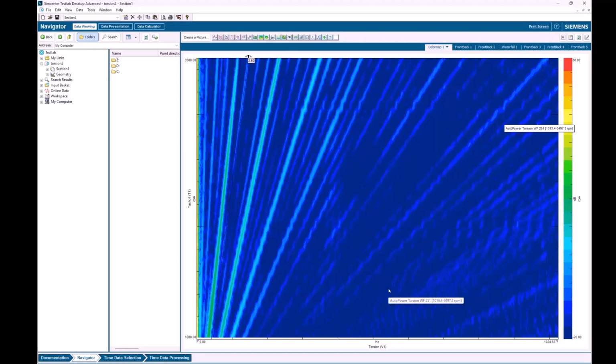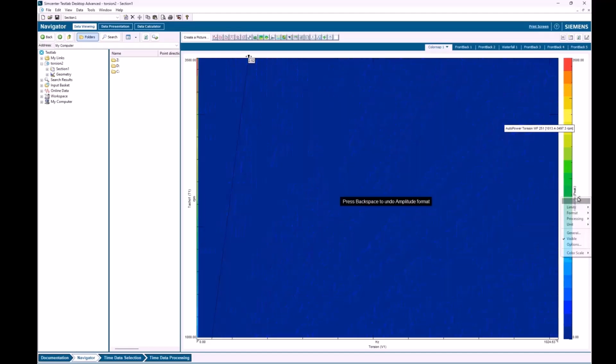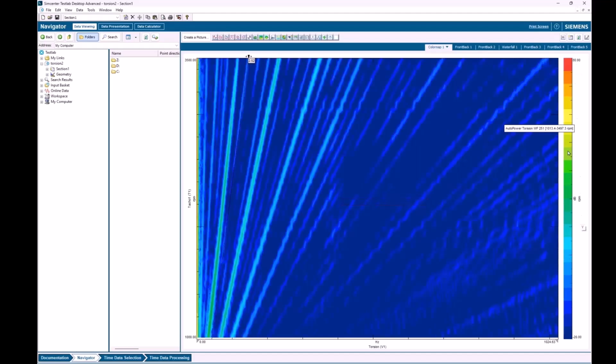This is a torsional RPM map, if you will, Charles, and it's got frequency here, RPM here. That's the overall RPM. And then it has the RPM, and maybe just to color it a little, we put it in dB so it was easier to see the torsional vibrations. But this is also RPM. And again, why is this one going up to 80 RPM and this one going up to 3,500? So on the left-hand side of the y-axis, we have the overall RPM, and then on the right color scale, that's the fluctuation that we're seeing as it's going.